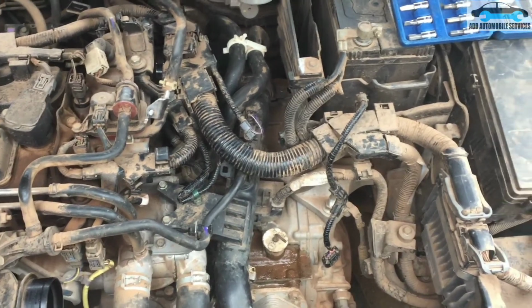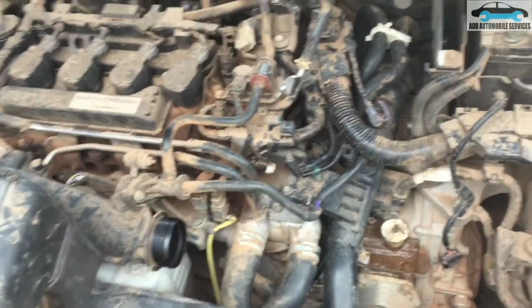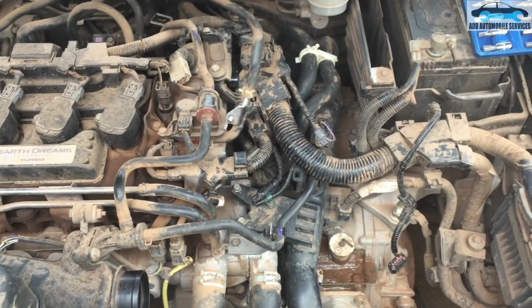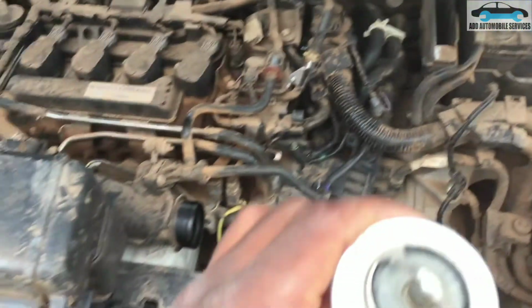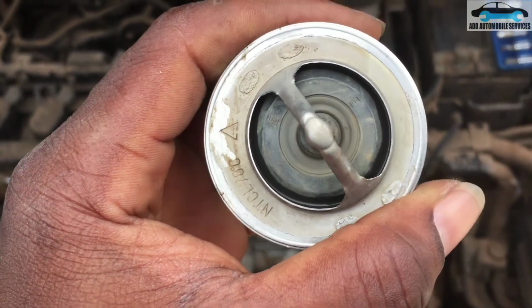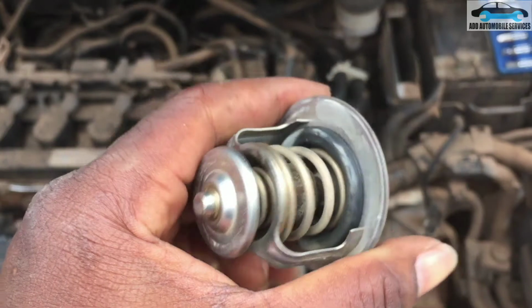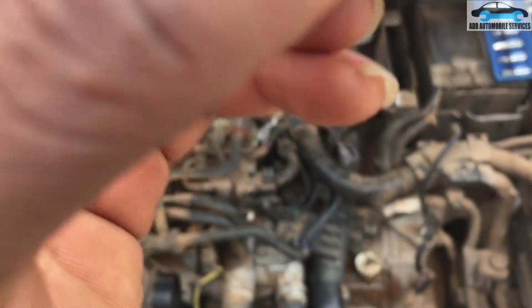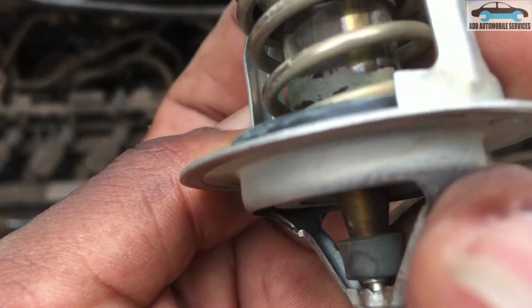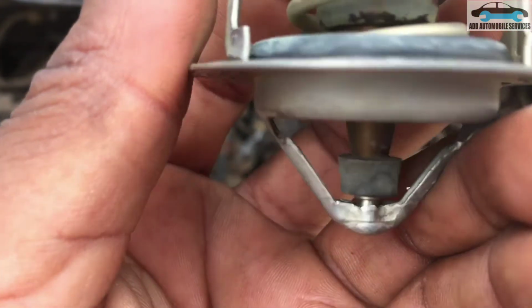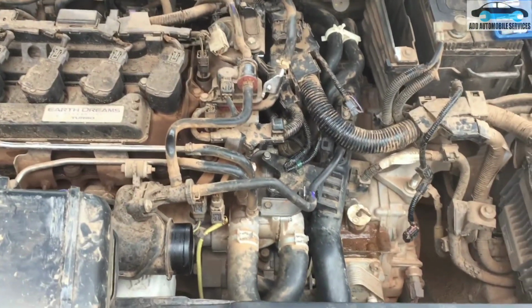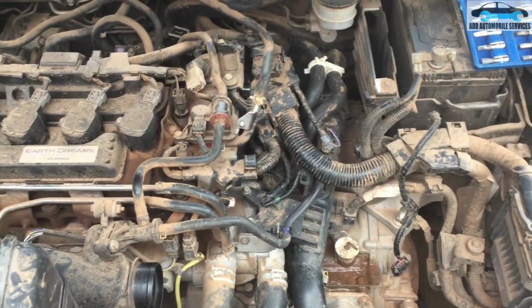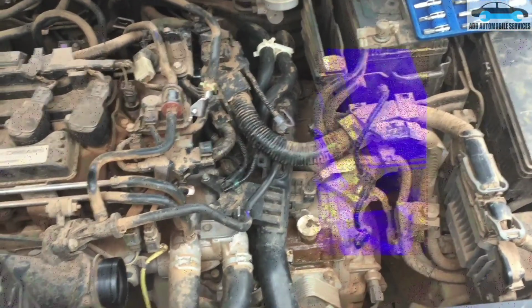If the temperature difference is not that much and the car is able to drive perfectly, then that means it's from the thermostat, it's getting stuck. It has 75 on it, so that means within 75 degrees it should start opening, and it looks like there is some sticking mark on it. So what I'll do now is I'll just drive it and give the customer the feedback. They will know what to do. If it is a thermostat, I'll let him prepare and get one, then we fix it.